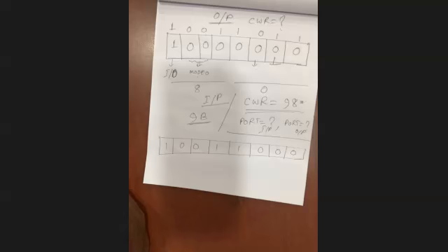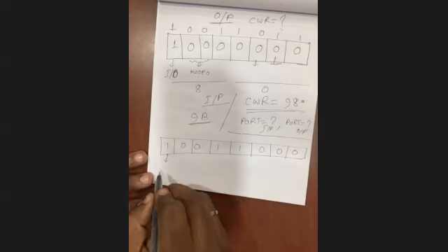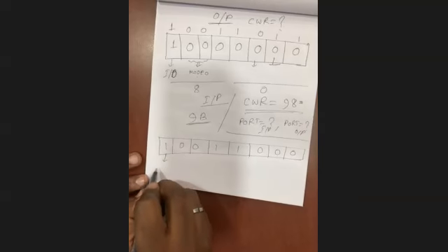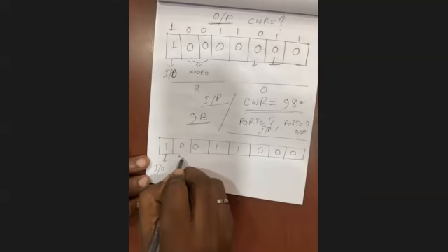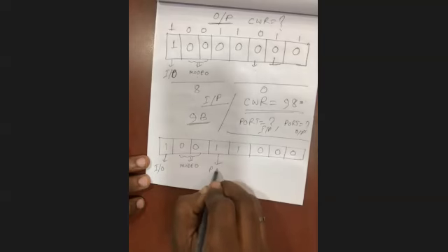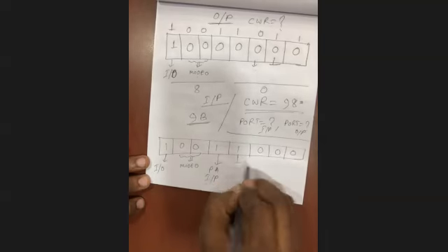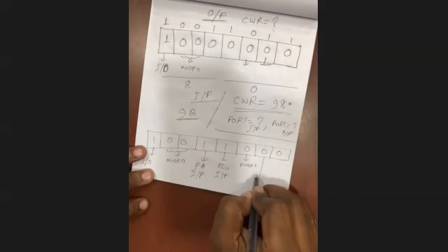So 1 is nothing but IO mode. 0 0 is nothing but mode 0. 1 is nothing but PA input. 1 is nothing but PC upper input. Again group B in mode 0. Again PB.